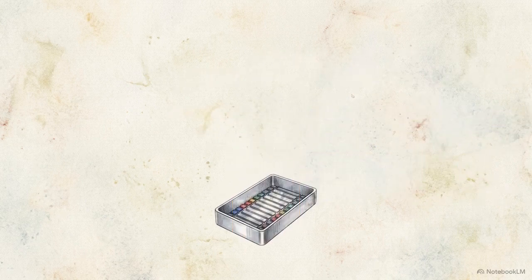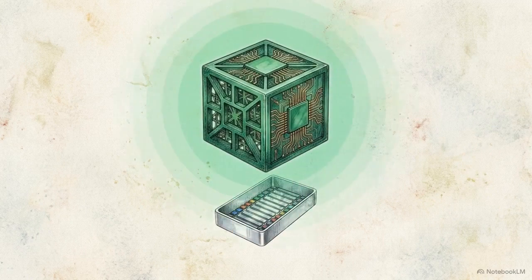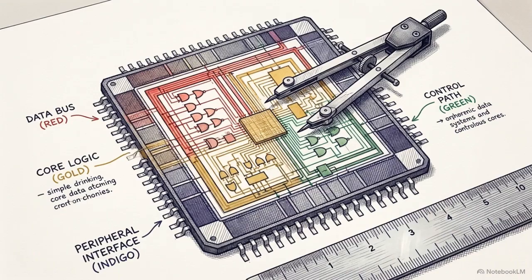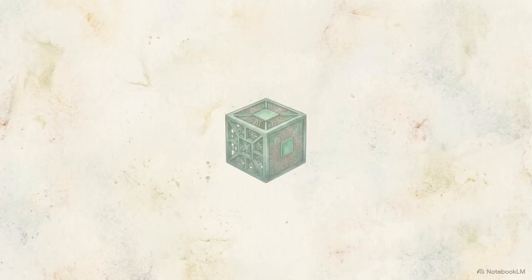You could strip out the recurrent layers and use purely spatial 3D convolutions instead. That avoids the operator error, but a full 3D convolution processing every pixel across every frame instantly overruns the SRAM limits. Functional offline sign language recognition requires rebuilding the architecture from first principles, mathematically factorizing spatial temporal processing so that every operation remains strictly within the limits of integer-only hardware.